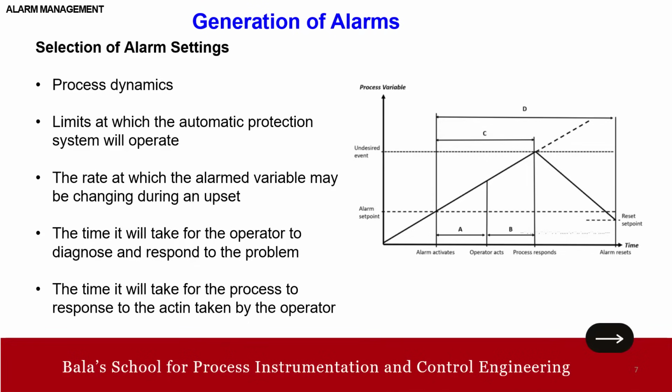Okay. Now I want to explain with this. You see, friends, basically, this shows how the set point of an alarm with an absolute set point should be defined, taking into account the time it takes for the operator to act. For example, you see here the alarm activates here, right? And the process starts responding here, right?